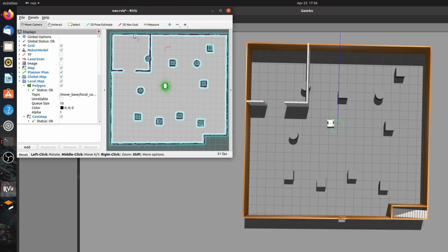Now we can see there are some more graphics on this map, and these are generated by the cost map. Basically what these are doing is setting boundaries for the robot. It takes the map created from SLAM, and it takes the parameters that you give it and creates boundaries for places that the robot can't go, because if it goes to these places, it will be hitting one of these boundaries. We also have here this cloud of green arrows.